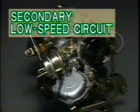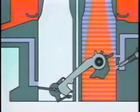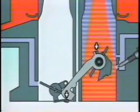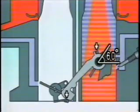Let's look at the secondary low-speed circuit for the secondary barrel. If the primary throttle valve opens more than 60 degrees, the cam in the kick-up system will force the secondary throttle valve to open slightly. And then the secondary slow port causes fuel to be delivered to the intake manifold.